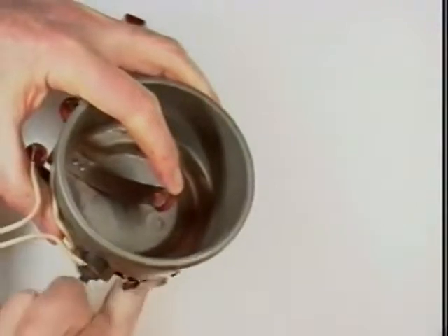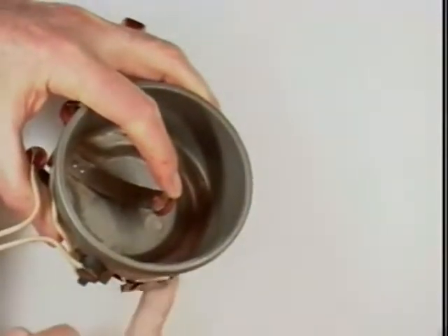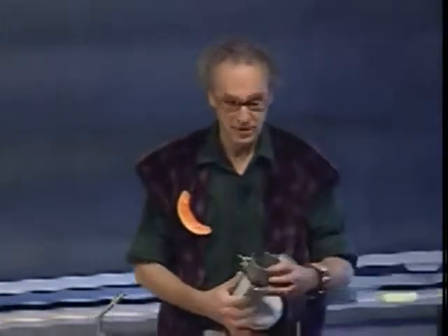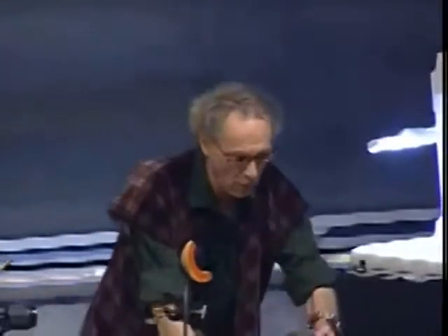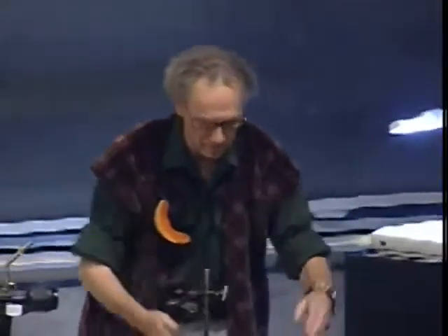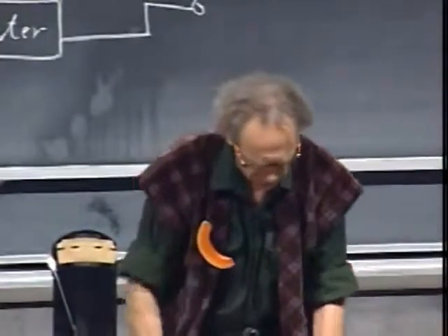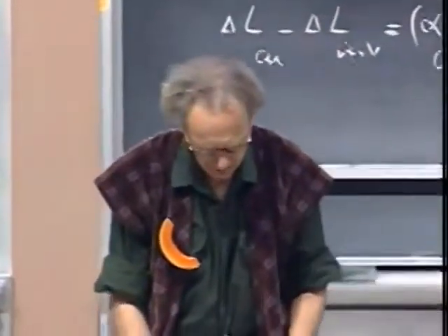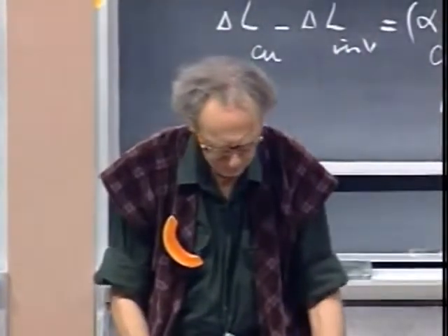there is a hole there. This is the hole. And the water comes out, and when the bimetal is closed, then it closes off that hole. So it's an amazing, simple idea. The criterion for letting the water go through the coffee is simply when the water reaches that temperature, close to boiling, and you have your bimetal control it. So bimetals, in many ways, control matters. Thermostats, in this case, they act like a valve.